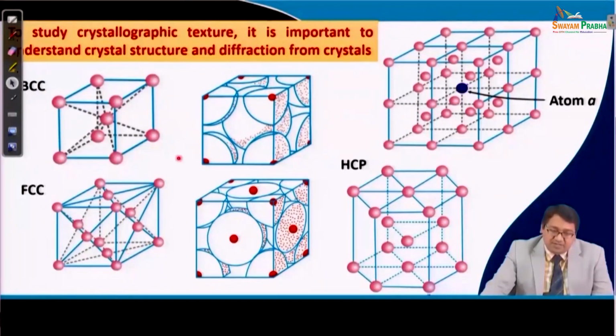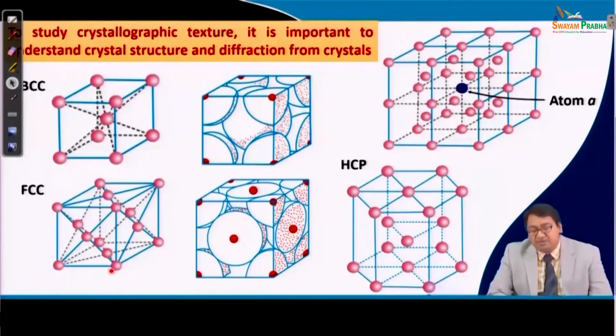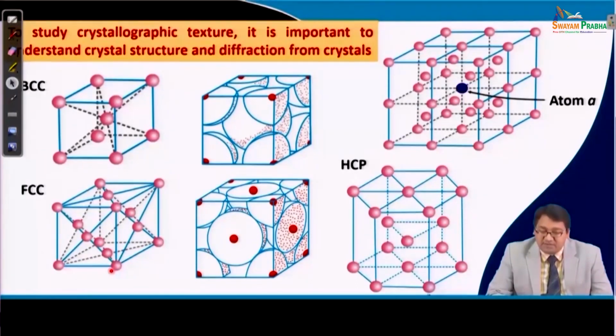Yes, of course, the stacking fault energy is also present in the body centered cubic materials, but you see face centered cubic, for example, aluminum alloy have a high stacking fault energy, copper has a medium stacking fault energy, brass a low stacking fault energy, and therefore, their behavior differs